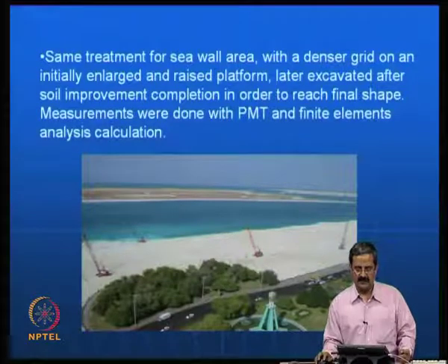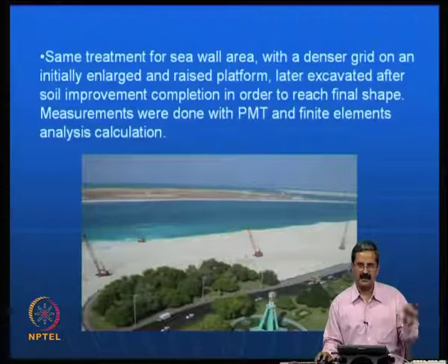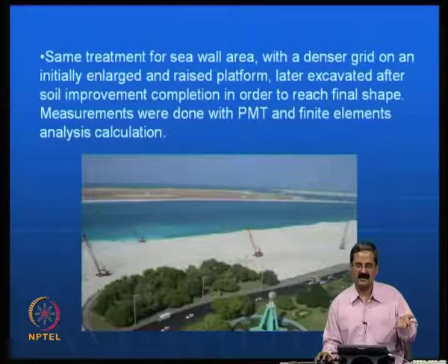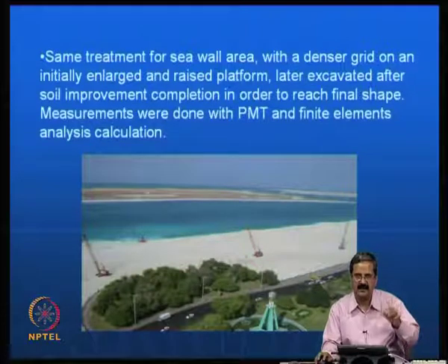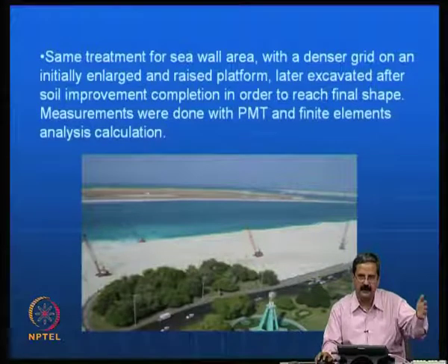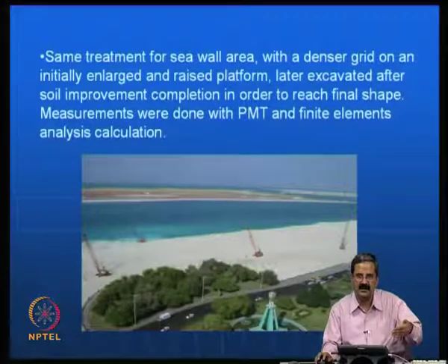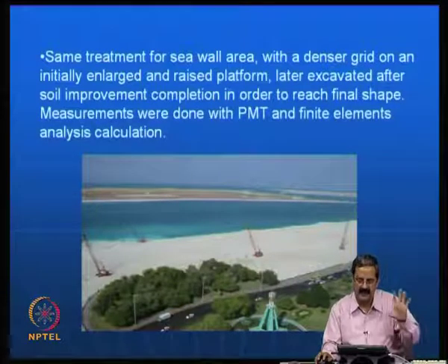And in this technique, we are able to see the design, where we have used a simple method in which you can design based on the weight available. You can design the height of drop and the spacing for the required depth of improvement. The required depth depends on, for example, 2B as a significant zone. If you have a footing of width B, 2B is the significant depth of the pressure bulb. So one must be able to calculate the significant zone.